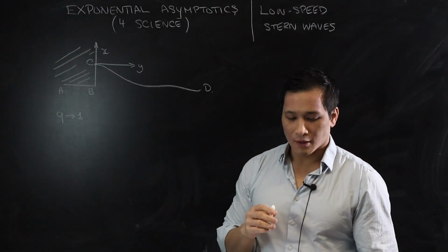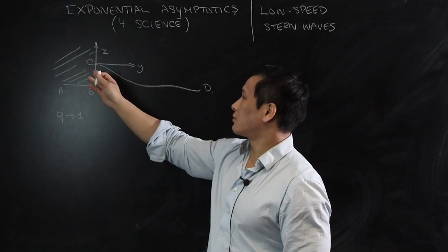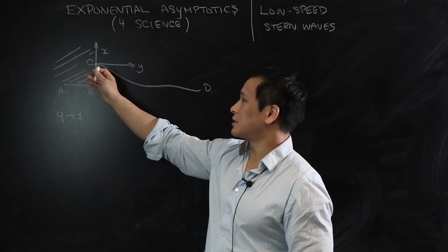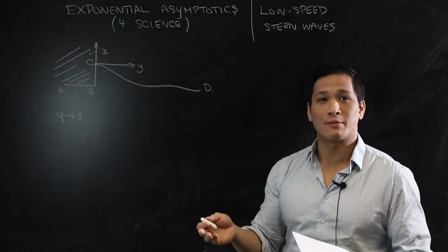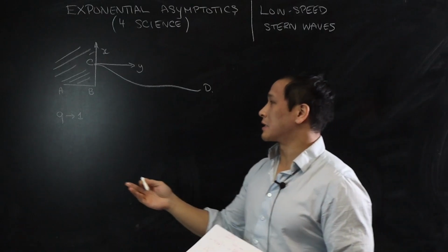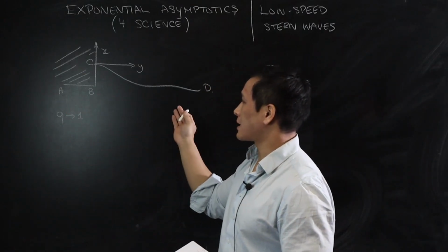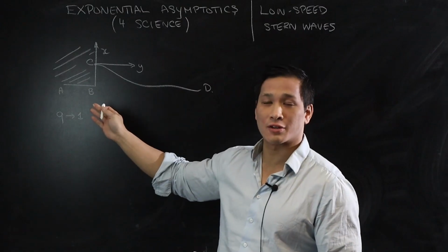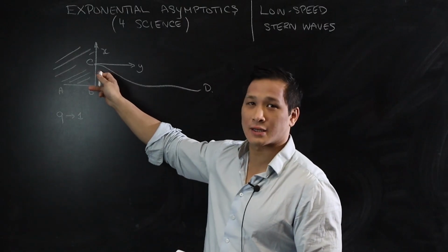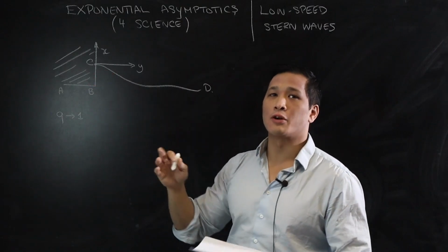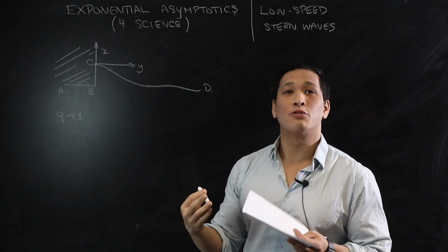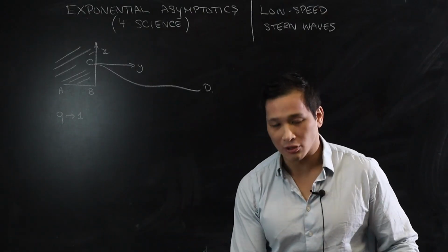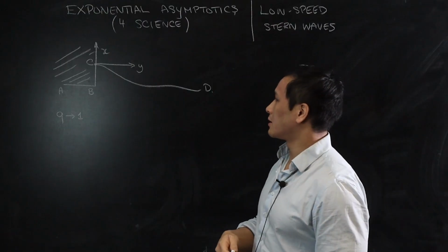Okay? We set up our coordinate system so that y is equal to 0 is at this stagnation point. So we're going to make the assumption, it's not meant to be obvious, that as the flow goes past the rear edge or the stern of the ship, it's going to separate at a stagnation point here, which is going to be largely what's going to happen if it's slow speed, or low speed fluid waves.